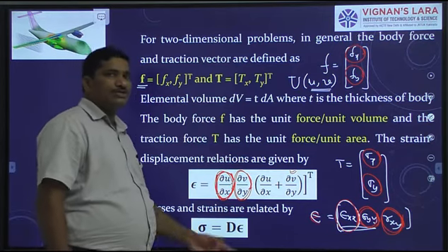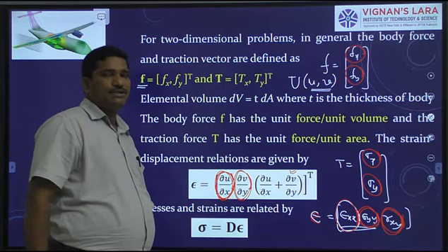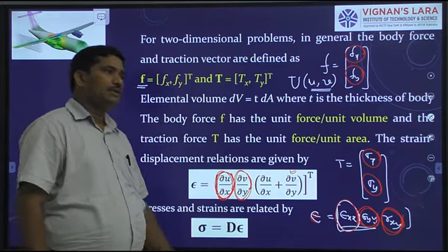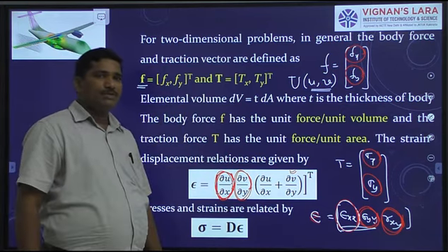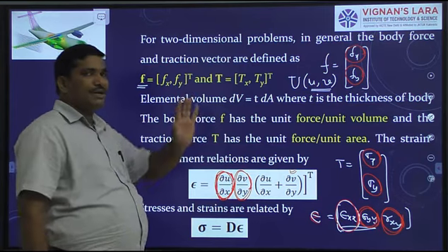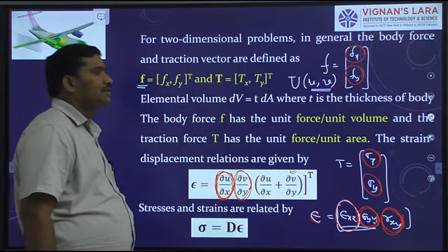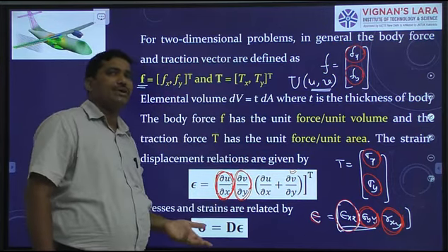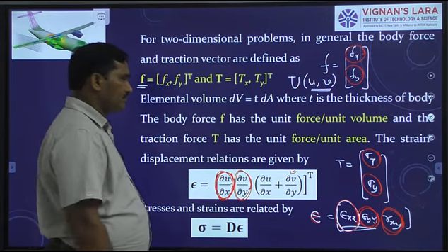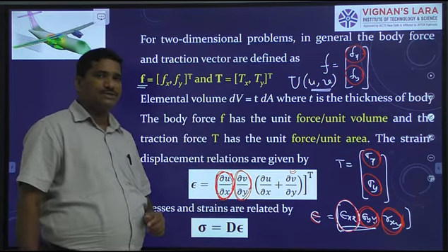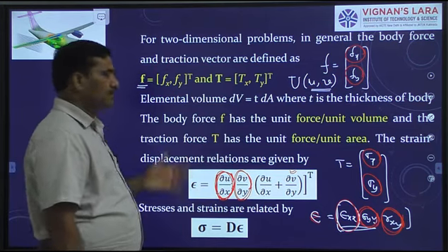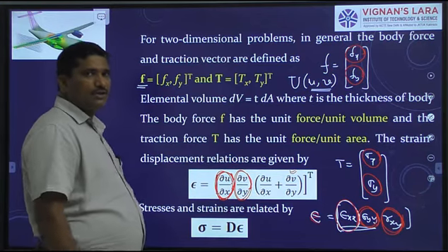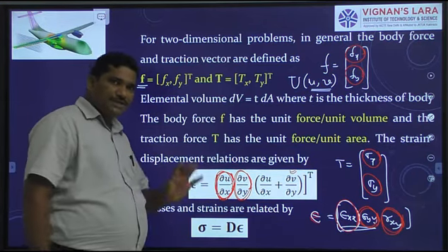Once you get the strain, you can write the stress strain relations. We know that for two-dimensional problems, we can write the stress strain relations considering the two-dimensional problem as the plane stress case or plane strain case.